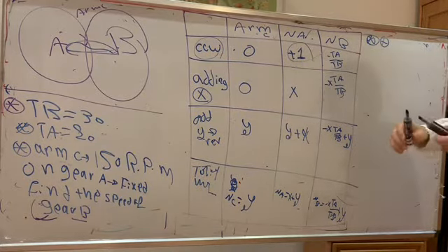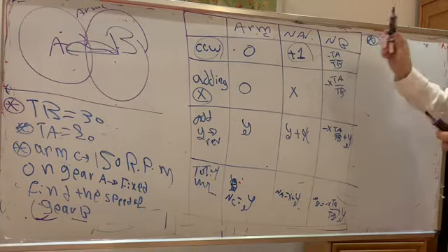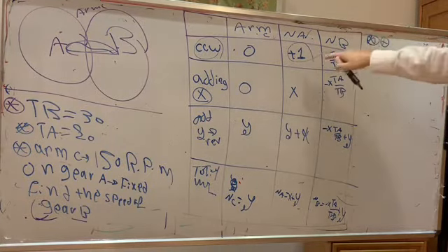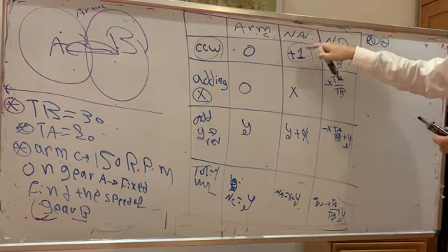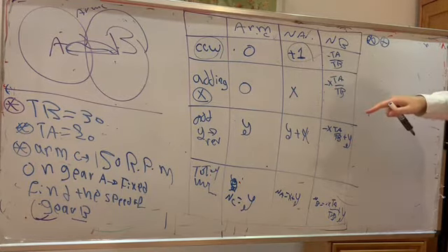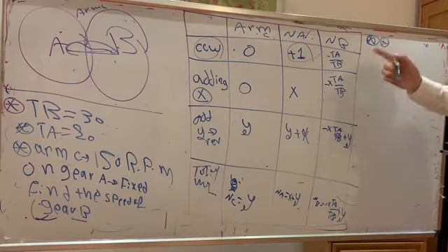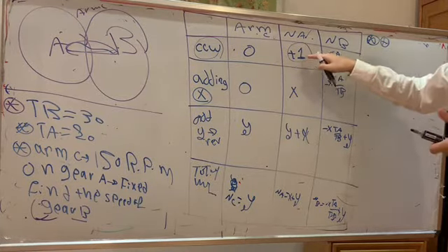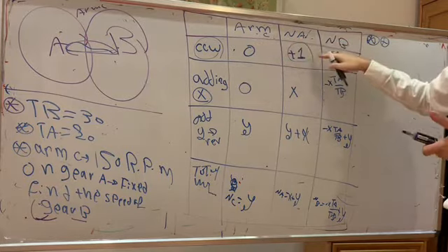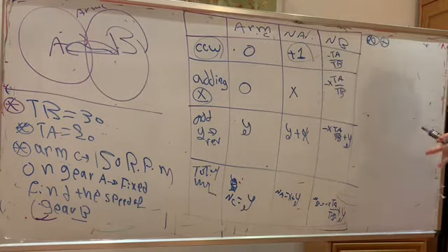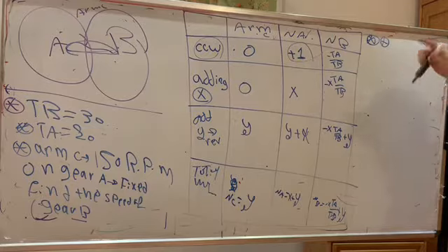The arm C actually rotates counterclockwise with gear A, so for gear A directly I put +1. I put it as the input. Why? Because I explained it in the previous video, I will not repeat. +1 counterclockwise, the input, because it rotates with gear B. Now moving on to NB, this simple gear, is it external or internal? It is external because it's meshing from the outside.